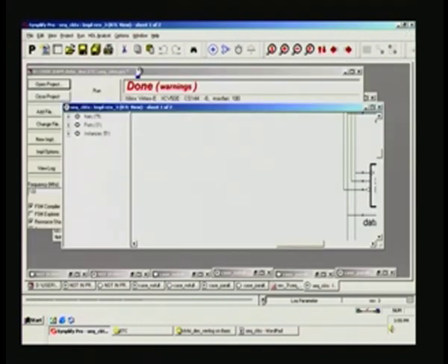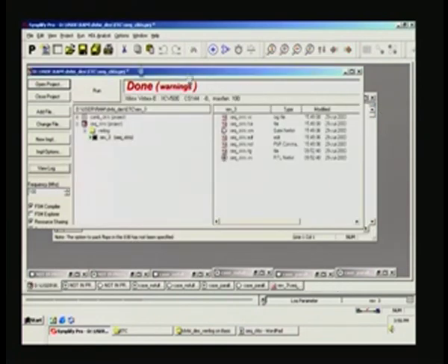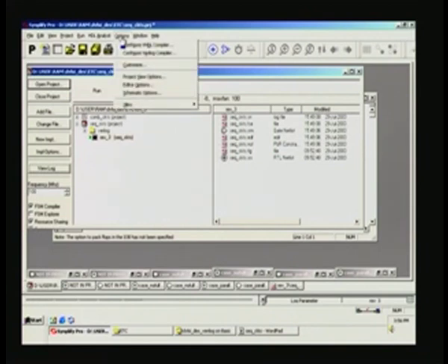and now what we are going to see is how we invoke the Xilinx place and route and learn about the tool. So, we have an options here. Just click on that options, then at the tail end you will have Xilinx, and within Xilinx you move on to this, you have start design manager, start floor planner, then start ISE project navigator.